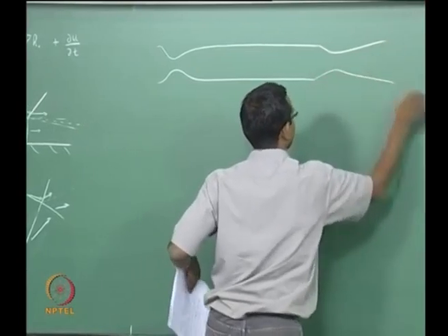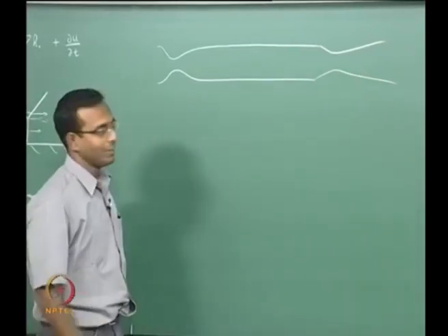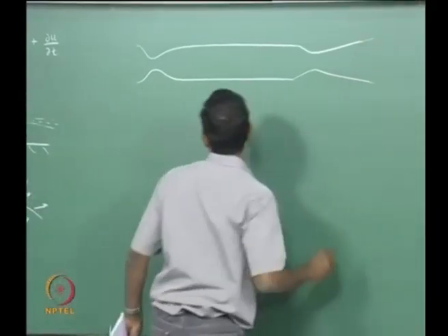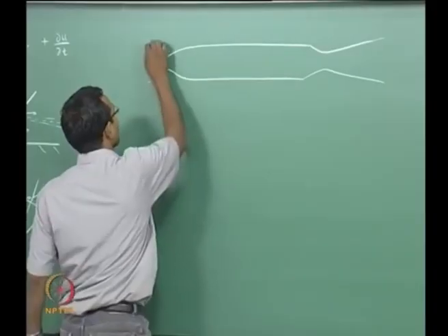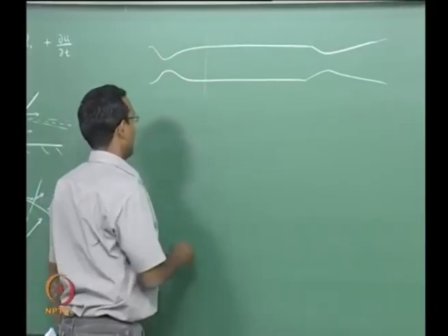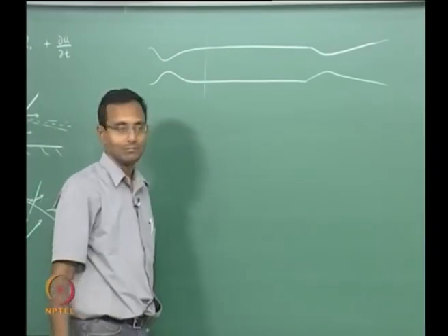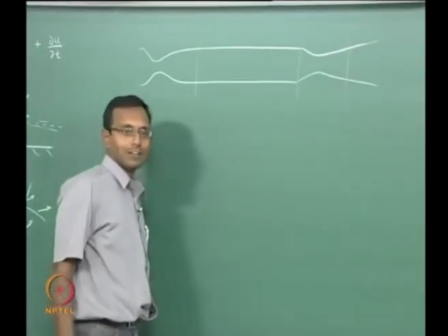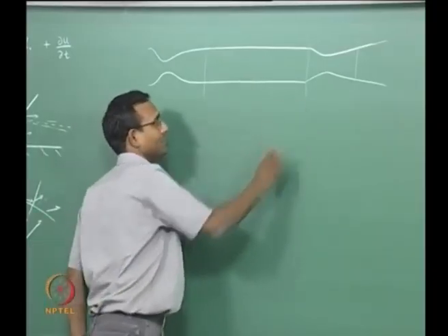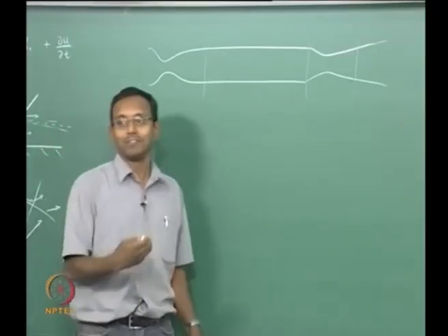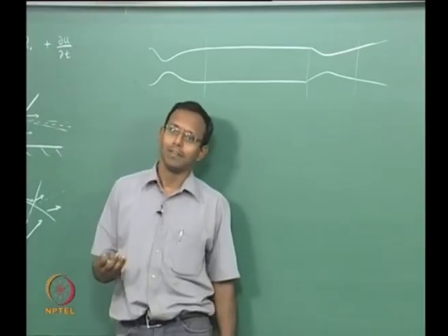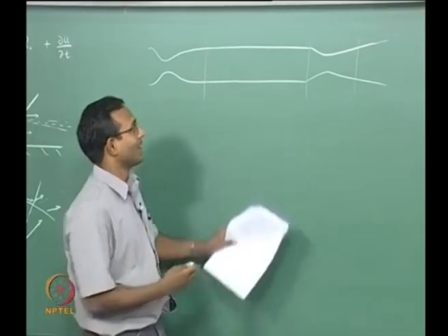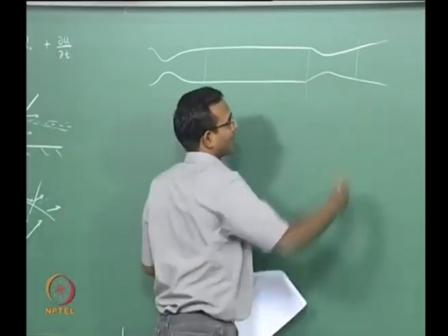a flow field like this, okay, very common, we will deal with it later. A very common flow field like this, I am going to say for this nozzle like shape up to here, I will neglect friction, and this nozzle like shape here I will neglect friction, and this intermediate region which is very long I will consider friction. Okay. Typically this is the simplest way to include friction, very easy to do compared to friction along with area variation in this particular case.